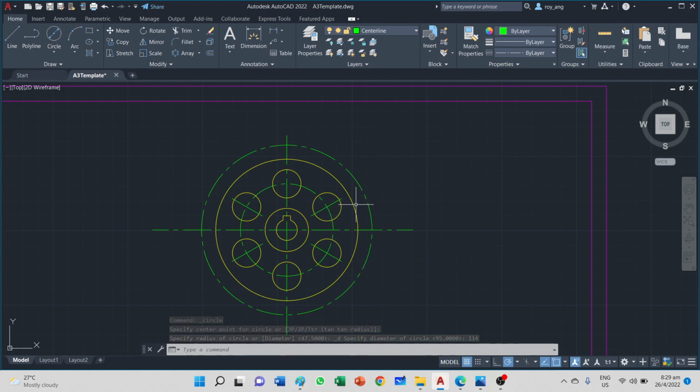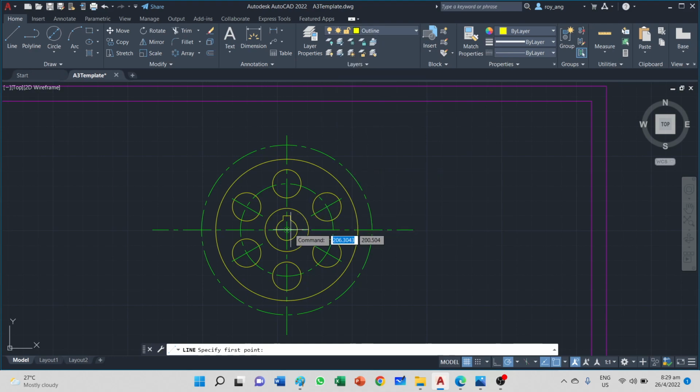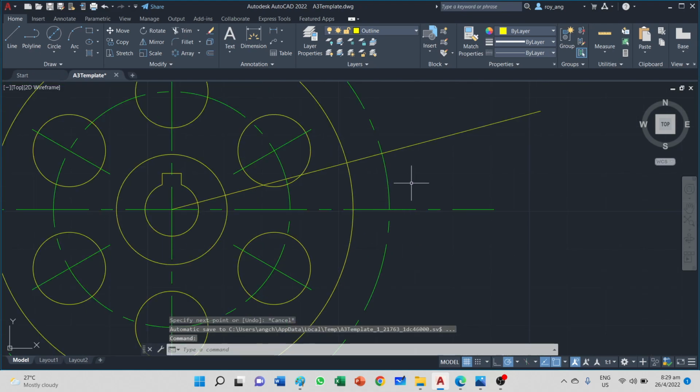Now how do we go about drawing the sharp edge over there? We can create a construction line, or we can create an outline. It's okay, and we give a value of the outline, maybe 100, tab, and this angle that we want to draw, the angle that is given to us is 15. So we are using the relative polar coordinates. And from here you zoom in.